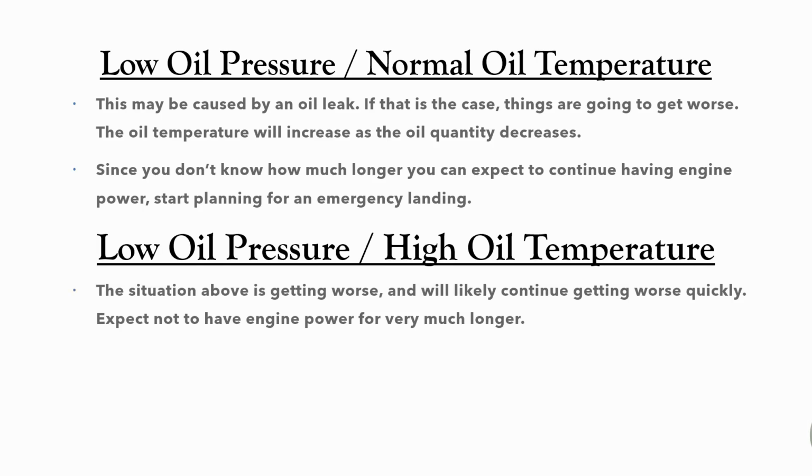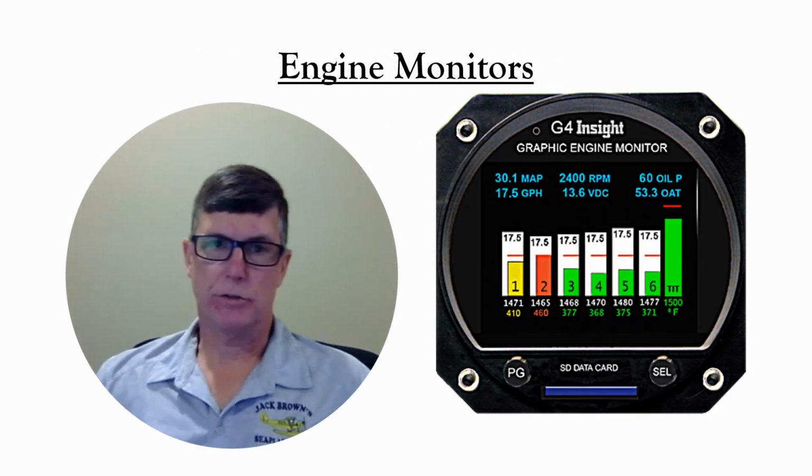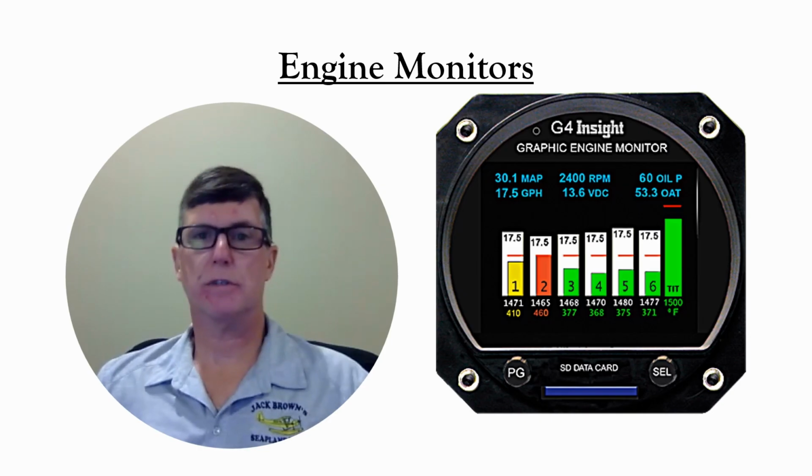If you have low oil pressure combined with high oil temperature, then you can stop hoping that it's an oil pressure gauge problem. The situation is going to get worse, and it's going to start getting worse quickly. You should expect not to have engine power very much longer and start planning for an emergency landing that will be happening soon.